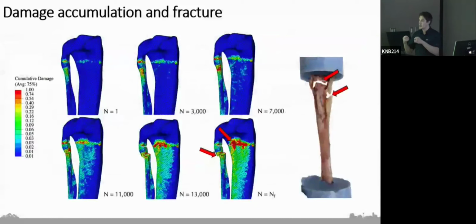Now, on the individual element level, we wouldn't model the direction or the shape or orientation of that crack or that void. But what we do see across a number of elements is an interesting fracture pattern. And we hope that that fracture pattern is due to strain, because we use a strain-based damage model.